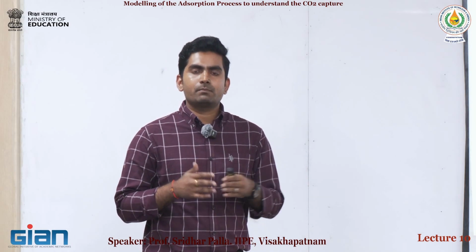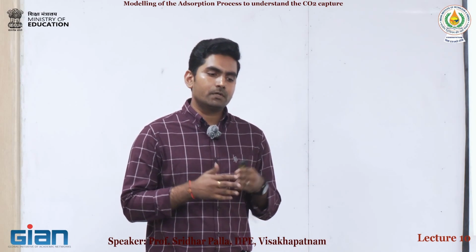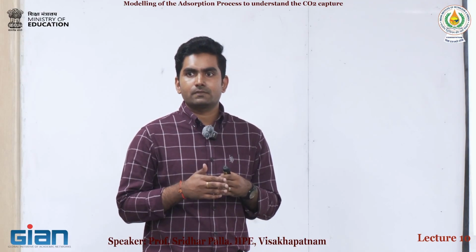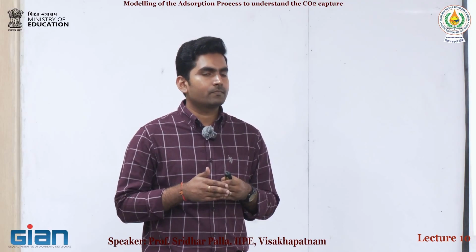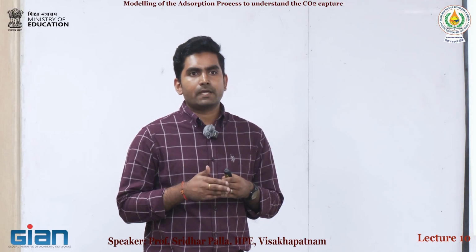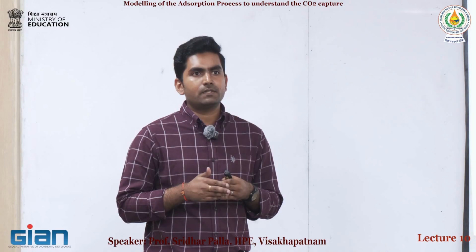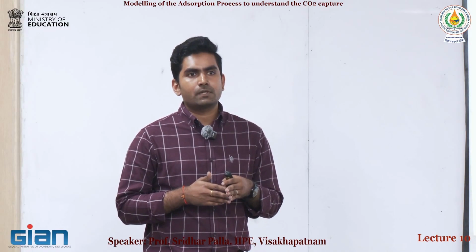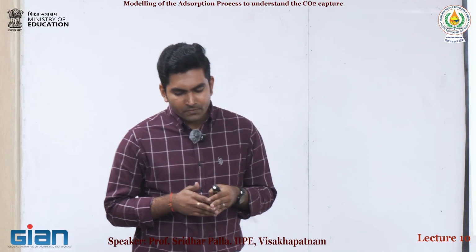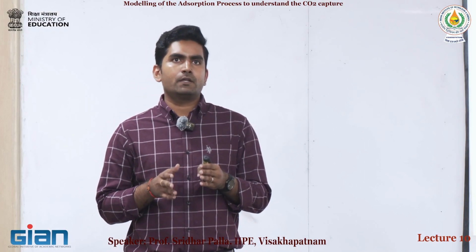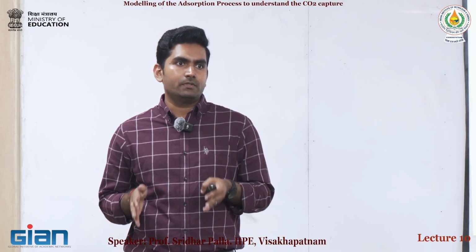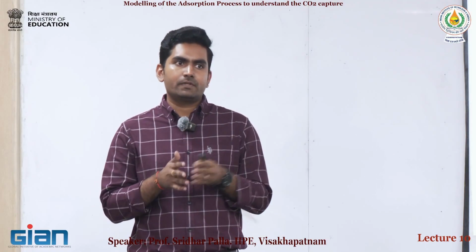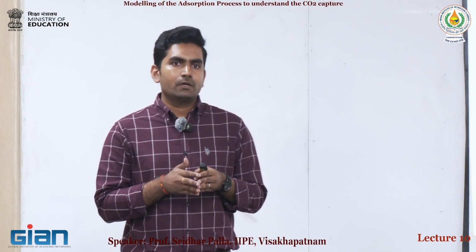In the case of post-combustion capture, we burn the fossil fuel and it produces flue gas. Along with that, CO2 will also come. So we will install our capture setup to separate the CO2 from the rest of the gases. That is post-combustion capture. In both cases, the location of the packed bed adsorber will change, whether it is before or after the combustion process.